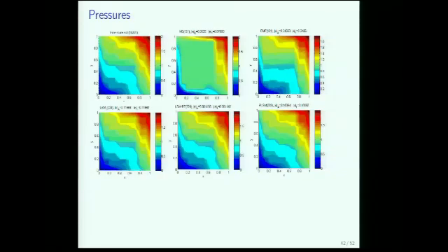If you use the multi-scale finite element method with linear boundary conditions, this will be like a worst case scenario, and you can see that the error is very large. You can definitely tune the boundary condition and get a better estimate, but that's not the goal here. I just want to pick one of them. Errors are about 90% if you do that. Energy minimizing errors are about 25%.